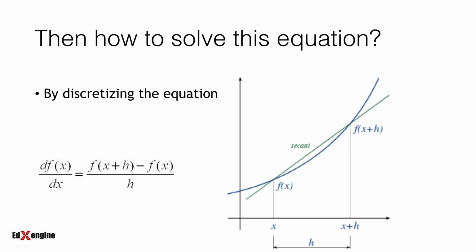So how do we then solve it? These equations are first of all continuous. That is, they are valid at each and every point in time and space. However, if we convert these equations so that they can apply on a discrete domain, then we can convert these PDEs into algebraic equations. This process is called numerical discretization. This process introduces a lot of errors, but at least provides us a way to solve these equations.